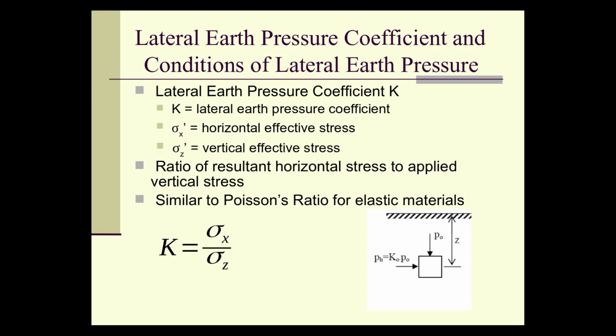If we have a sample and we put it into compression, depending upon what material it is and how much force we put on it, it's going to bulge at the sides. If we try to contain that in some kind of container, then we're going to trap it, and we're going to develop stress as that mass attempts to deflect laterally. The volume which is displaced by us pushing down on it is going to want to move out. When it can't, then stress results.